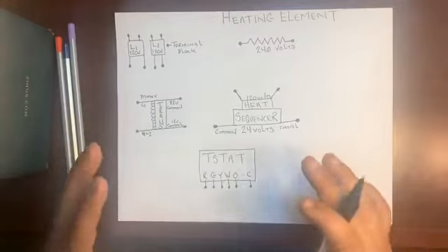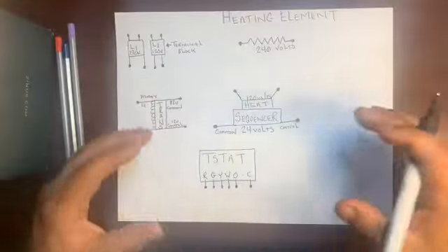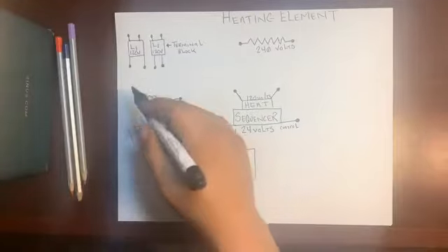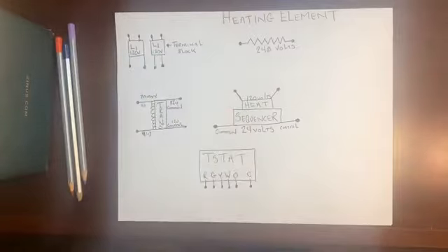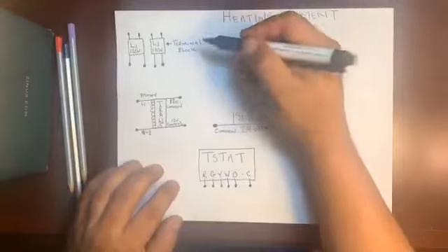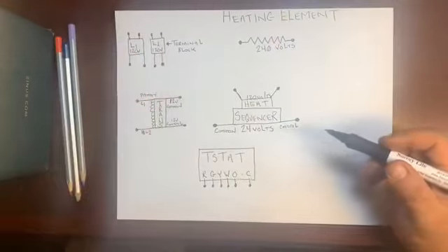Now we got the basic low voltage diagram. Now we're gonna go back through it piece by piece and then fill in a few things. First thing, L1 and L2. Both bring in 120 volts. When they come into the system, they come in on what's called a terminal block. So our terminal block is what brings L1 and L2 into the air conditioner.